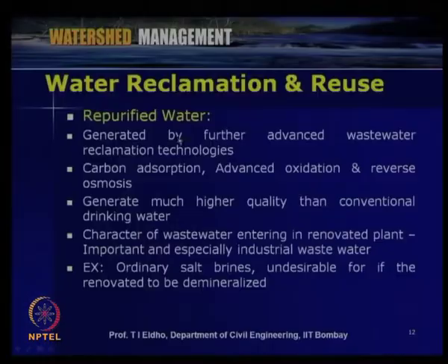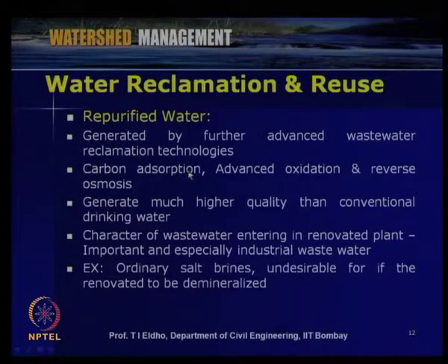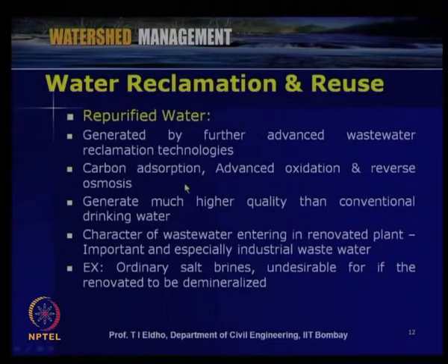The water generated by further advanced wastewater reclamation technologies, like carbon adsorption, advanced oxidation and reverse osmosis. As we discussed in the last lecture, with many of these advanced treatments the water becomes much more purified and of much higher quality than the conventional drinking water we take directly from rivers, lakes and other sources. So the character of wastewater entering the renovation plant is important, and especially where industrial wastewater is concerned, we have to see which way the treatment is to be given and what kind of reuse we are looking for.